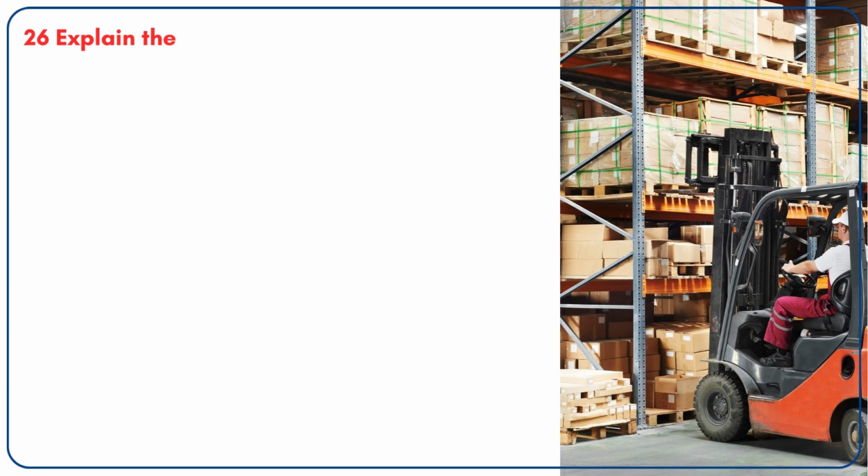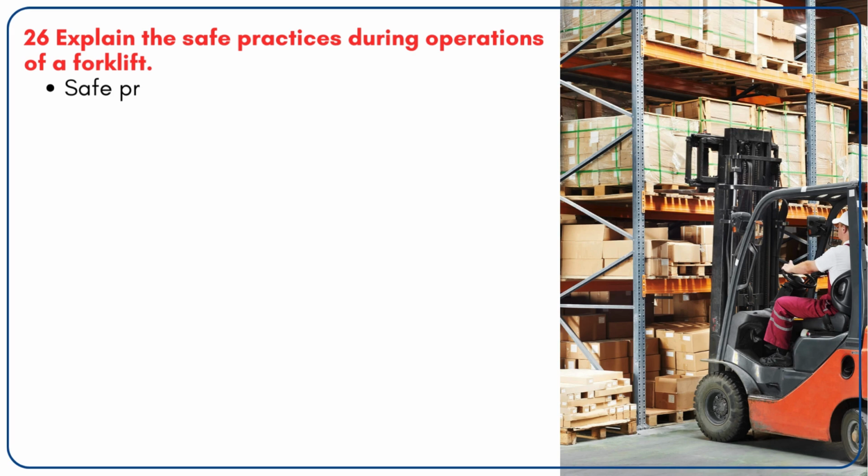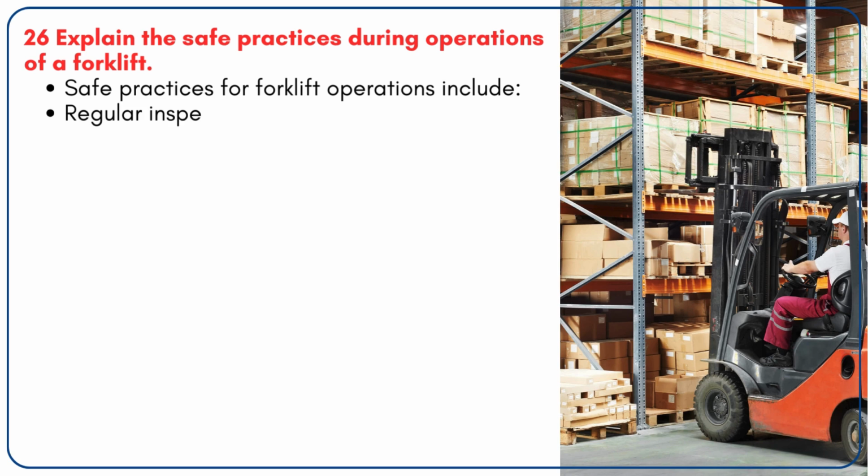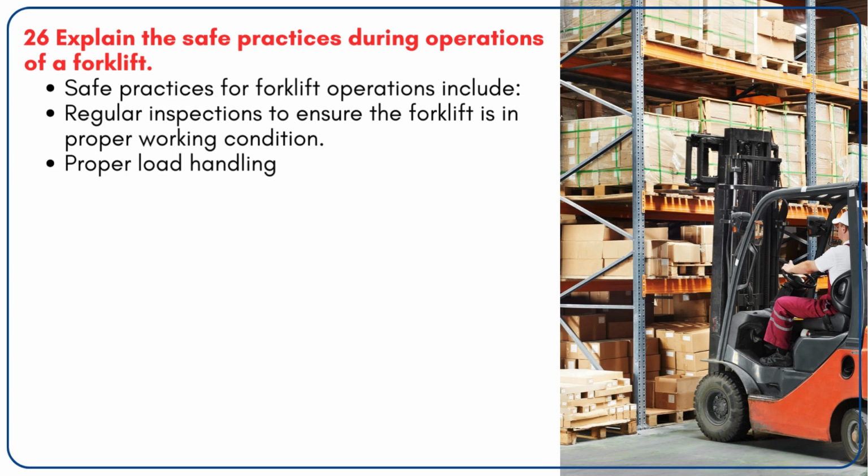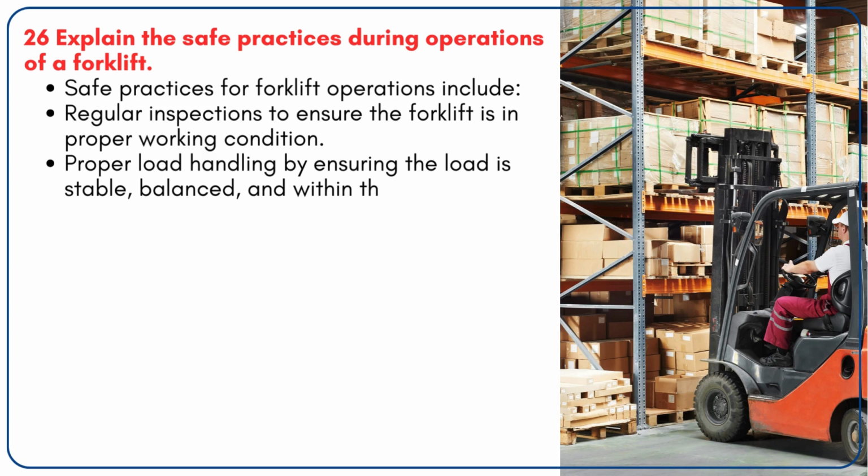26. Explain the safe practices during operations of a forklift. Safe practices for forklift operations include regular inspections to ensure the forklift is in proper working condition. Proper load handling by ensuring the load is stable, balanced, and within the forklift's weight capacity.